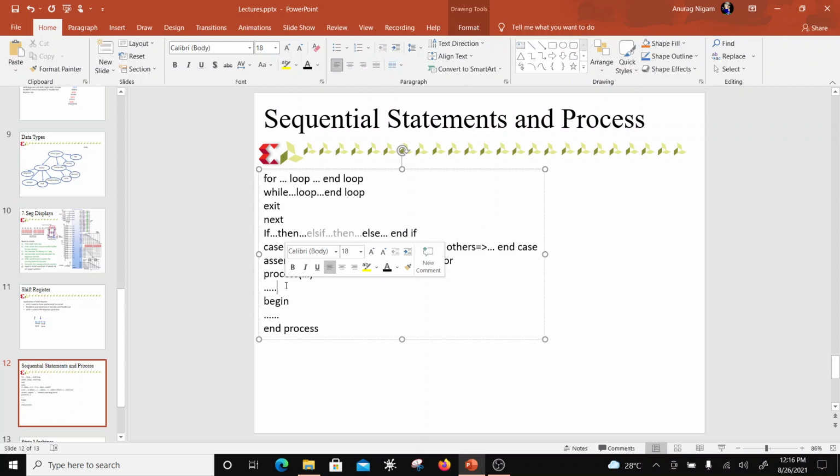They are sequential because the processor is itself sequential, so that's why the C language is familiar to them. Now, Verilog is kind of a derivation of C. So inherently Verilog is sequential. But then you have got parallel constructs in it, like an always block or something like that, right?